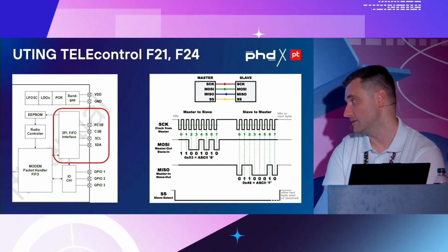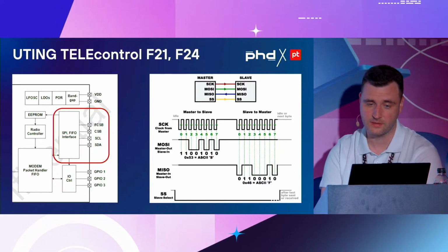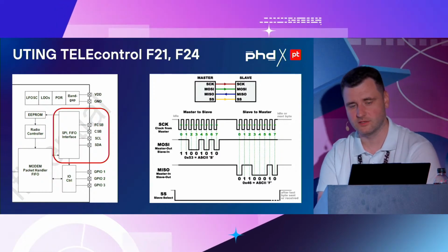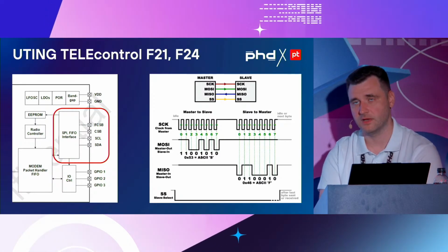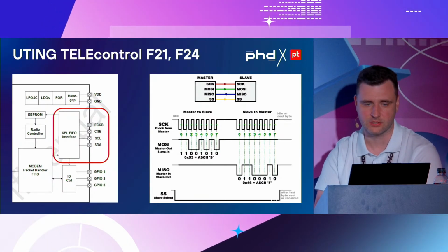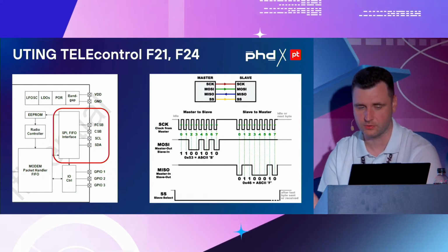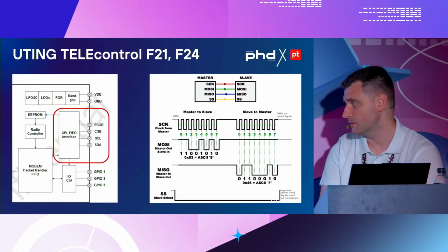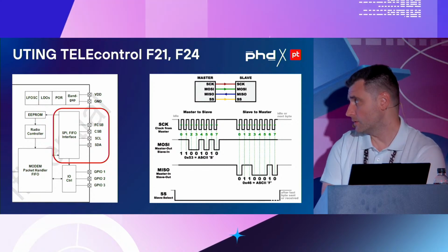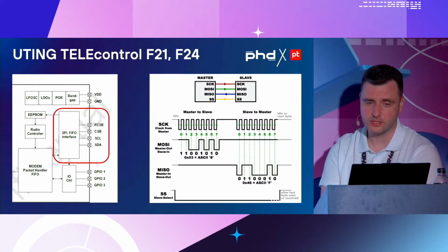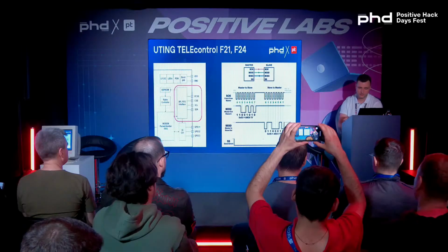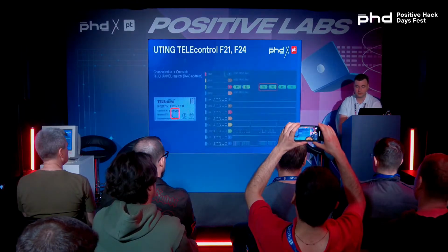For those who do not know what SPI is, it is a sequential, synchronous interface. The speed is about units of megahertz, and certainly there are faster ones. But the industrial solution would use about 500 kilohertz. And it can be analyzed by the cheapest logic analyzer.